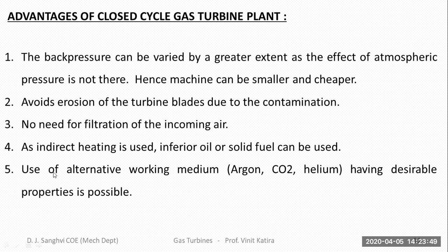Last point is you can use an alternative working medium like argon, CO2, helium, which has much more desirable properties. Since it is a closed system, there is no restriction to use only air as a working medium. You can use argon or helium, which has better thermodynamic properties as compared to air.